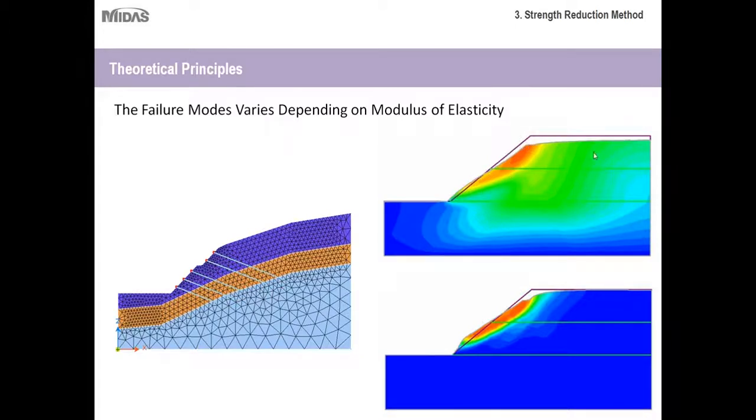But it also occurs, significantly, in the areas beyond the slope as well, or further away from the slope. But in this model here, the modulus of elasticity is much higher, so the materials anywhere are more resilient. So once again, deformation now only occurs near the base of the slope here. That's just a visual example of how much the modulus of elasticity can alter your results. So it's really important that you have your modulus of elasticity magnitude in there correctly, and that you have it lined up with the right material. Otherwise, you could get erroneously high or erroneously low deformations.